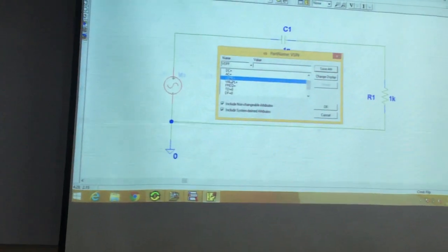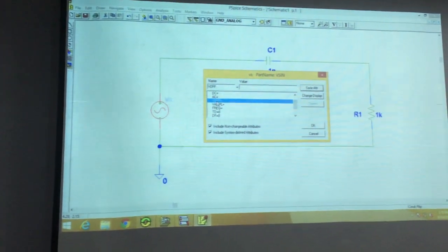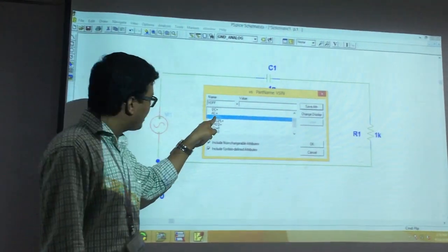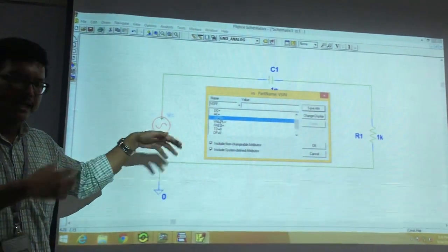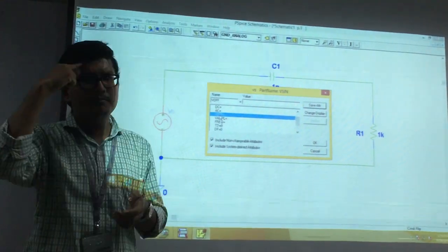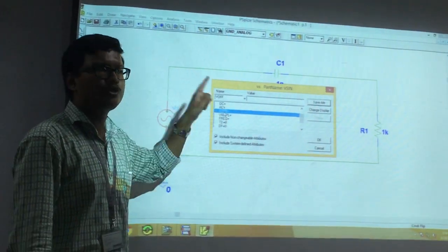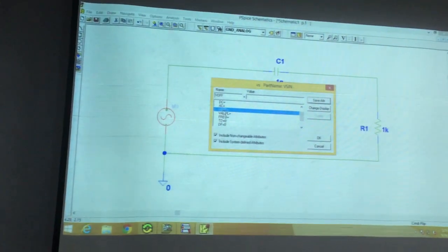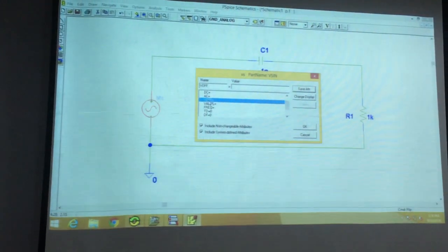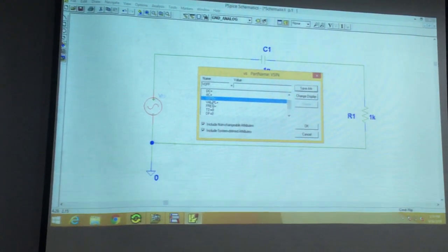something called VOFF. Okay? This is definitely not the amplitude, not the frequency, but then again, without this guy you cannot work with the circuit, without that guy you cannot work with this guy. Okay? So that's it. You don't need to know the definition. Just keep in mind whenever you use that VSIN guy, you set this property to 0 always. Okay? So VOFF basically a voltage. It should have the value 0 volt and that's it, done. You don't need to understand anything else about that. So I'm gonna set it to 0 volt.